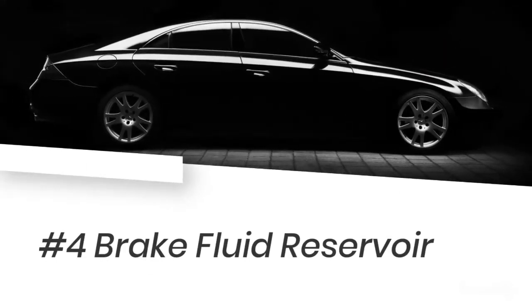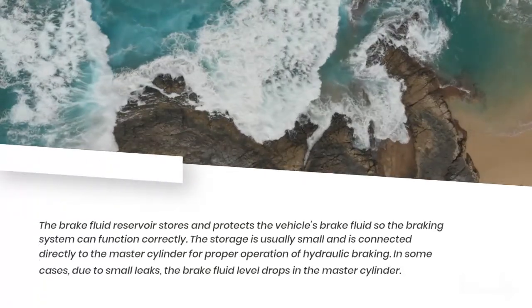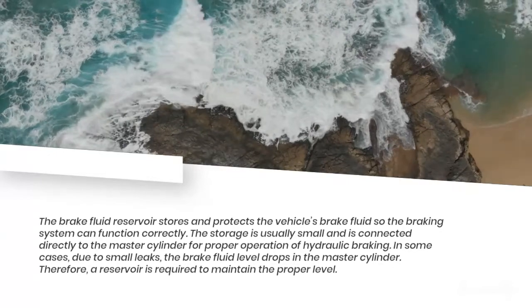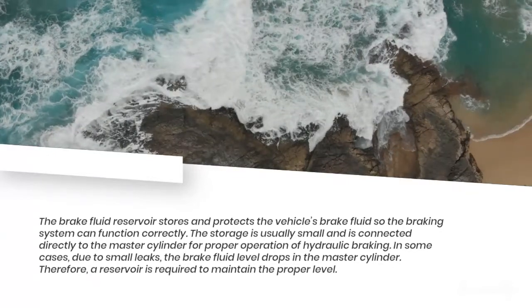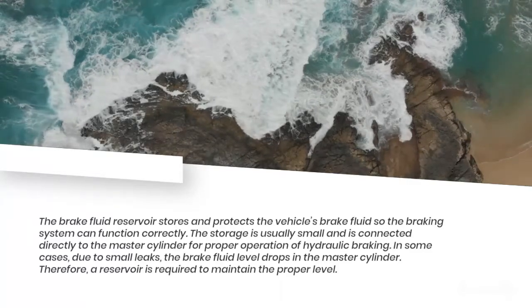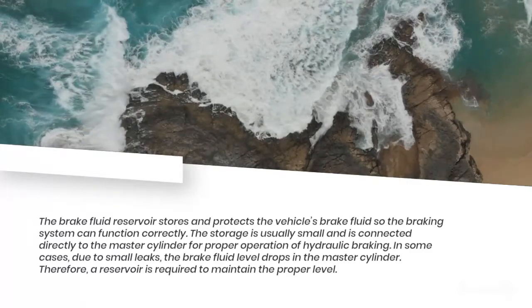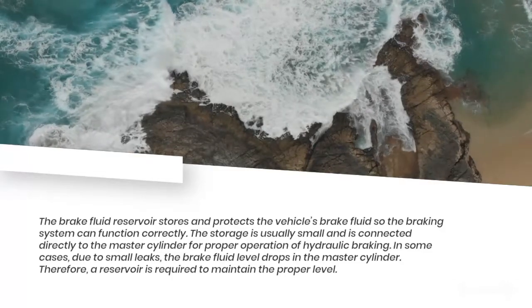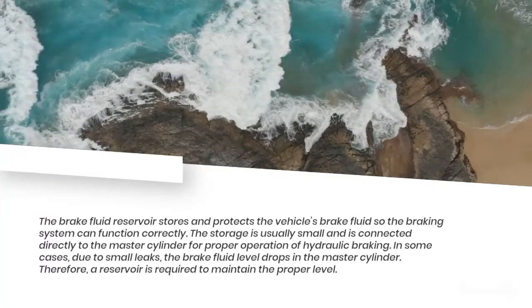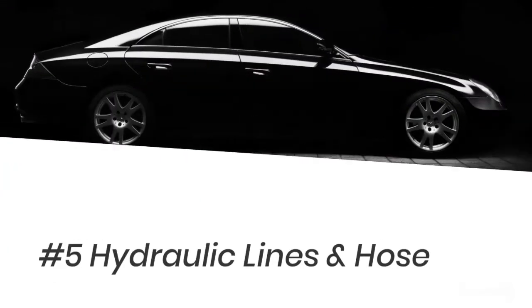Number 4. Brake fluid reservoir. The brake fluid reservoir stores and protects the vehicle's brake fluid so the braking system can function correctly. The reservoir is usually small and is connected directly to the master cylinder for proper operation of hydraulic braking. In some cases, due to small leaks, the brake fluid level drops in the master cylinder. Therefore, a reservoir is required to maintain the proper level.